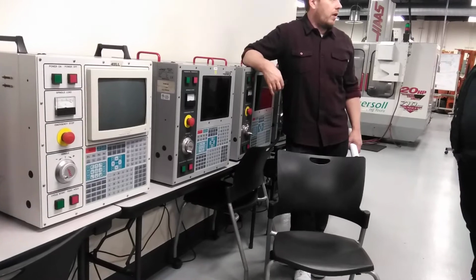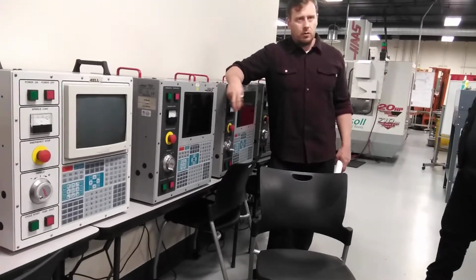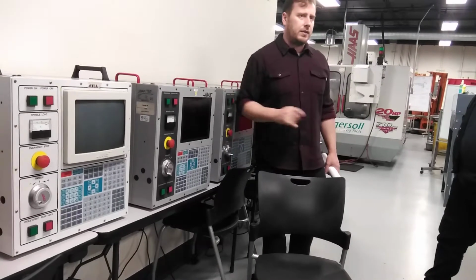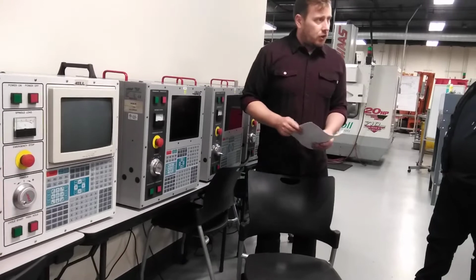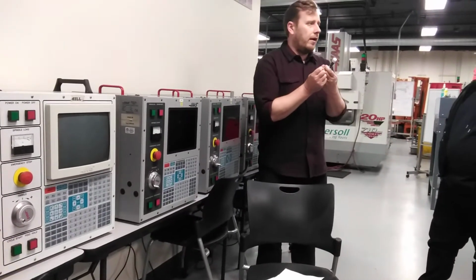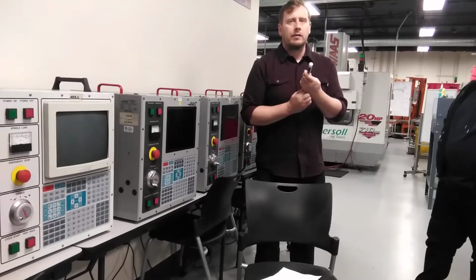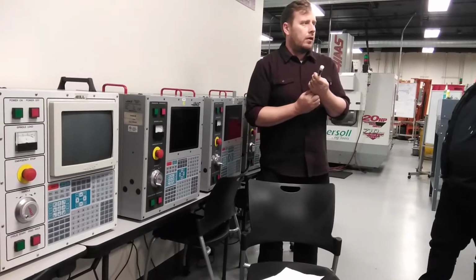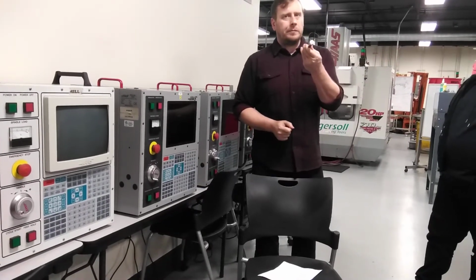The majority of programs out there in the industry use G41 and G42, so you got to understand how to use this. Right? So before you set your tool up at the machine, what should you do to it? How do you know it's 1/4 inch? Measure it. You need to measure it. When you measure it, what kind of measurement are you getting?